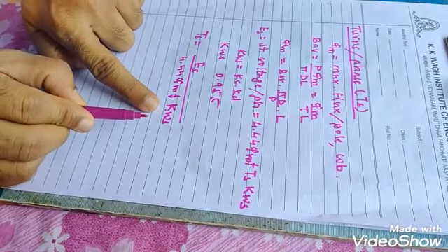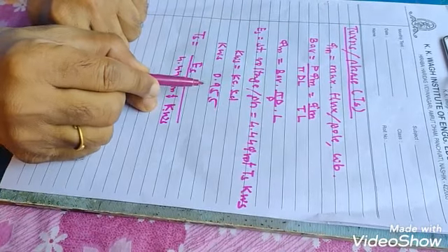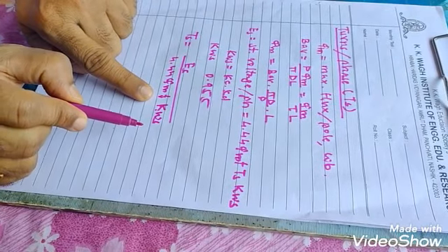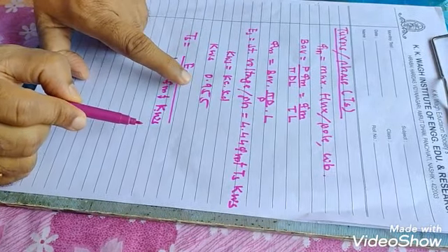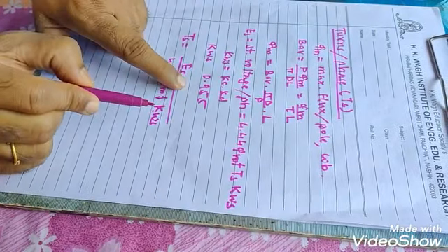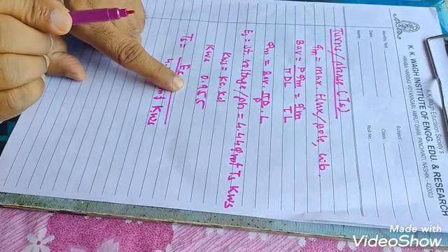Then Kws is the stator winding factor, which we assume as 0.955. f is the supply frequency and ES is the stator voltage per phase. ES depends on the connection of the stator winding.